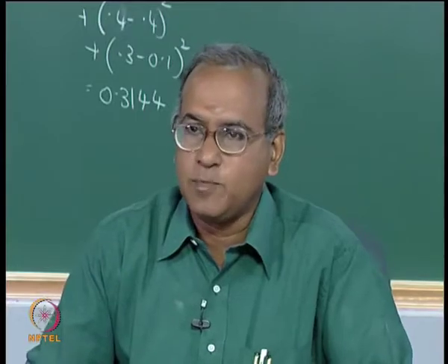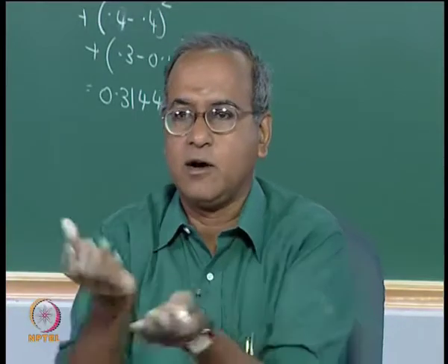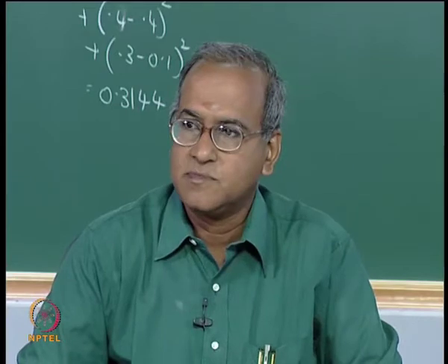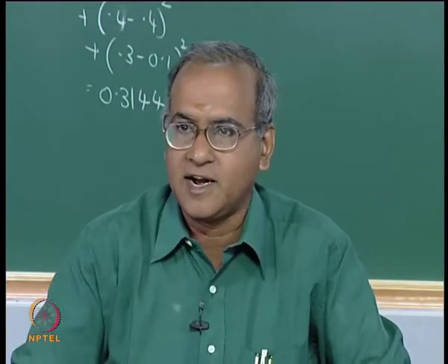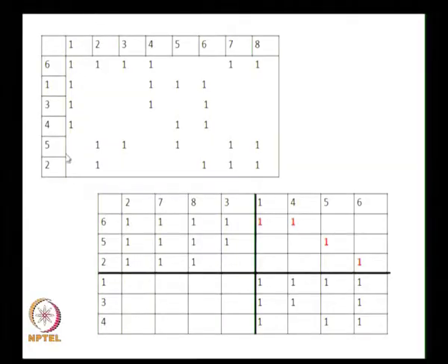Part subcontracting would be to entirely take out that part from the matrix. If we really have to do part subcontracting, then we have to take out, assuming that we duplicate 6, both 5 and 6, which will go completely away and will not be made in the cells. The entire part is outsourced. In such a case, the part families will be 2, 8, 7, 3 for the first cell and 1 and 4 for the second cell.